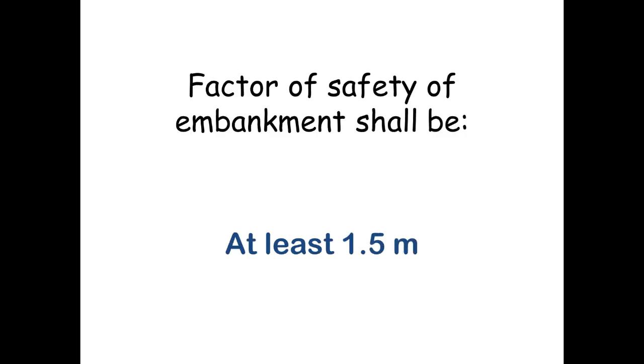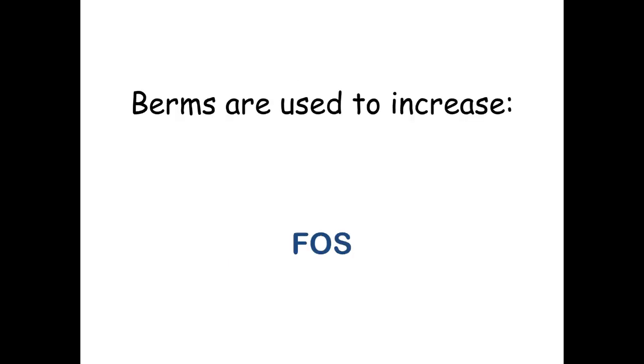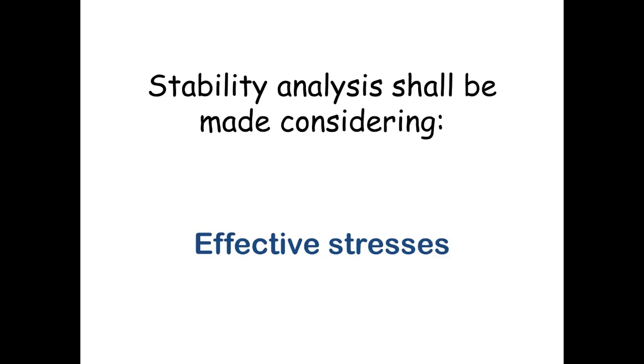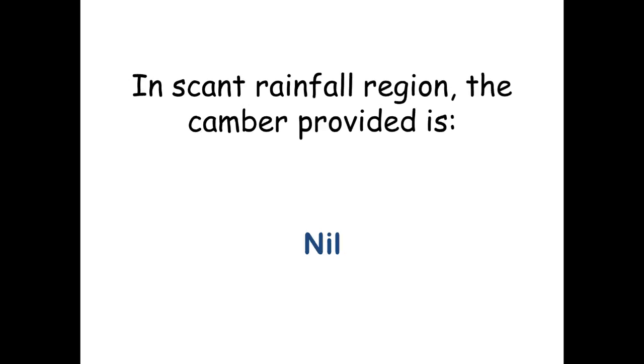Factor of safety of embankment shall be at least 1.5. Berms are used to increase factor of safety. Stability analysis shall be made considering effective stresses. In scant rainfall region, the camber provided is nil.